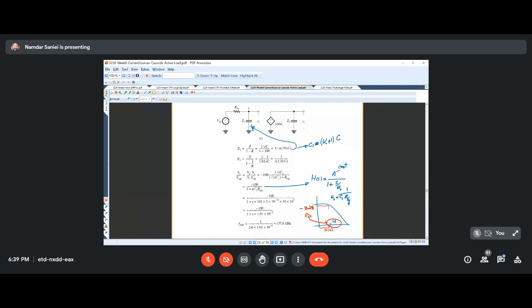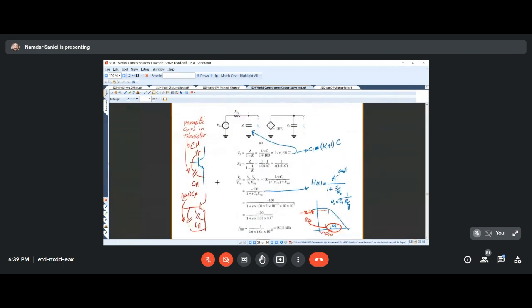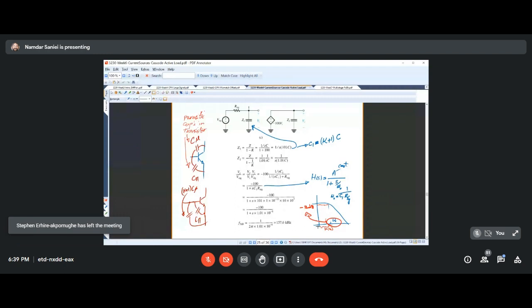And we realized that it acts like a low-pass filter, which basically kills the input frequency spectrum. And then we revealed that in a transistor, unfortunately, we do have a capacitor, which sits exactly between the base and collector, which is usually input and output. And therefore, if that gets amplified here on the input side, then we are going to lose a lot of bandwidth.